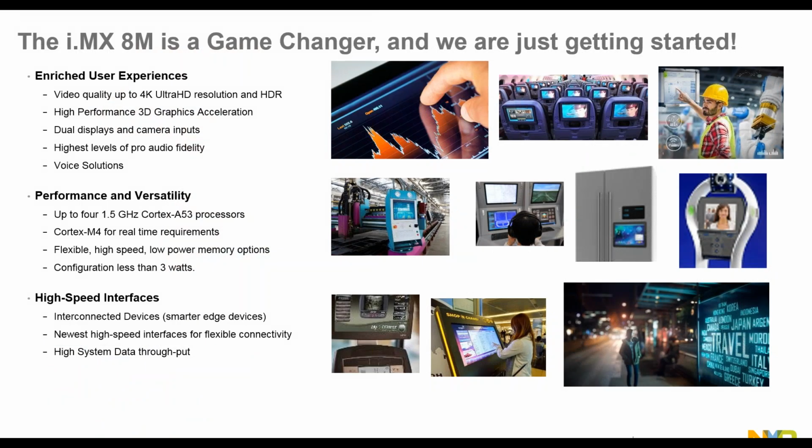So when you consider then hardware and application processor for your embedded design, you start to care about things like 4K decoder, 4K resolution, video capability with H.265 encoding decoding standard, 3D graphic acceleration that can provide you the performance, and Nick will show all the neat stuff you can do with it, benefiting from it. High fidelity audio, so you start to embed high quality audio in your design, not bringing that to external DSPs anymore.